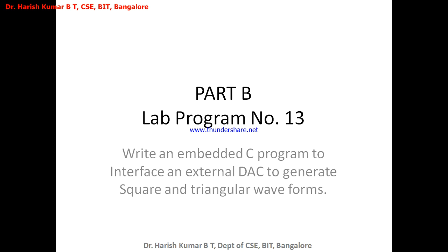Today we are going to understand the next lab program from part B. That is lab program number 13. The program is: write an embedded C program to interface an external DAC to generate square and triangular waveforms. In the previous session, you understood how to display a hello world message using the internal UART of LPC2148. Now today you're going to understand how to interface an external DAC to LPC2148 and generate a square and